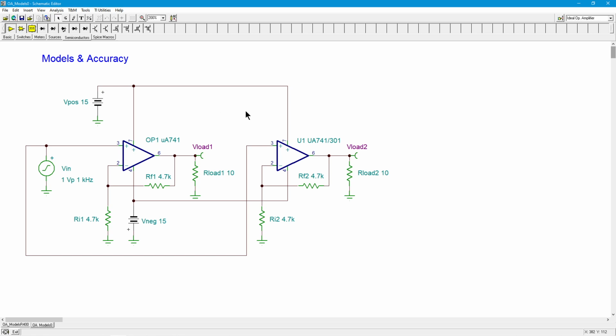It's not just something to deal with op amps. Whenever you're doing some kind of simulation, or just real world components, you always have to bear that in mind. What is the sort of variability you're going to get on real world components? How much accuracy do you need? Is the component model in the simulator sufficient for the kinds of simulations you're doing? If all I'm doing is some simple transient analysis to check gain and so forth, either one of these is great. If I'm really going to push a small load, this one proves to be a better model than this one. So you just have to be cognizant of that.